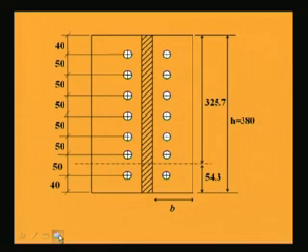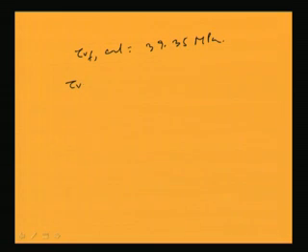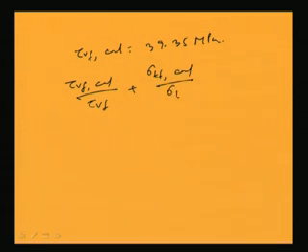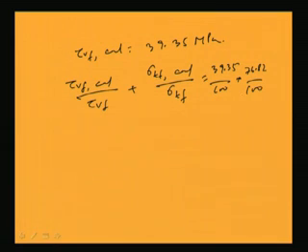After calculating this I will get the result as tau Vf cal as 39.35 MPa, right. So, now from the codal requirement I have to find out tau Vf cal by tau Vf plus sigma Tf cal by sigma Tf, which is equal to 39.35 by 100 plus 76.82 by 100. This is becoming 1.17, which is less than 1.4.